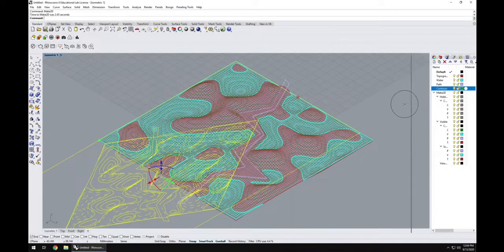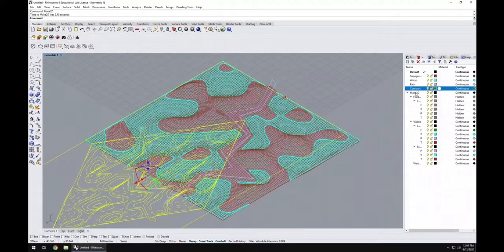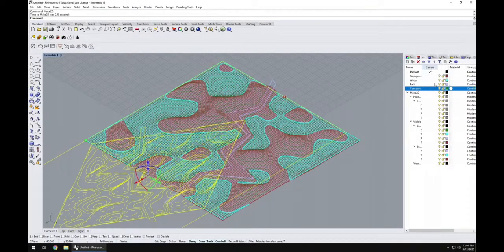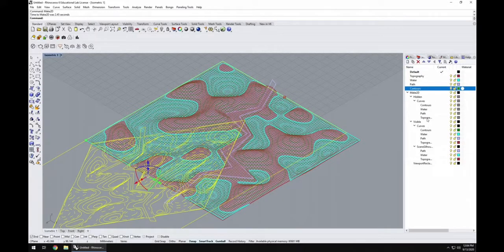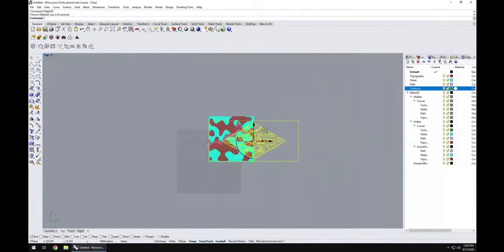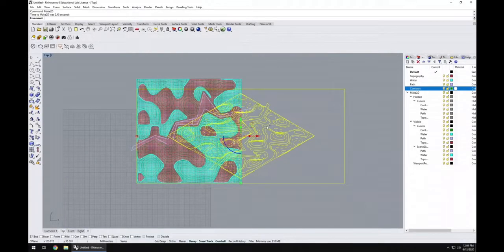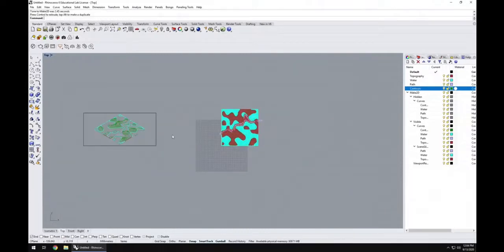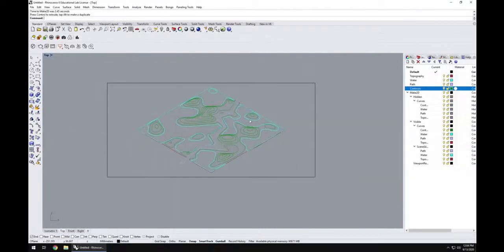As you can see, because we maintain the source layer, within this make 2D layer it's actually creating some sublayers which maintained our source layer, where the layer came from. It's going to save us tons of time when we go into Illustrator because all of these layers can be preserved in Illustrator. Now, while you have this selected, don't click on anything else. With this selected, go to top view, and as you can see, it's actually creating this make 2D view here. You just move it away while everything is selected. That's your make 2D drawing.